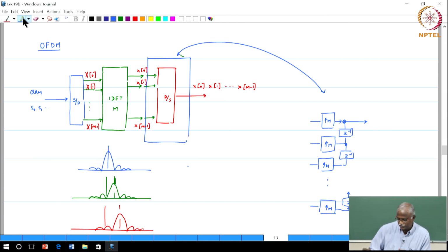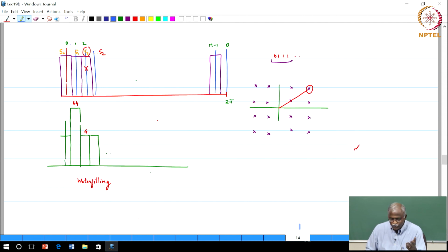with this particular structure. The IDFT and this structure actually implements a filter bank for you. So when you apply them, you automatically get the translation from time division multiplexing to frequency division multiplexing. And of course this also gives you a lot more insight into when you do not transmit on a particular carrier, and when you boost the power of a particular carrier. Again, all of these are flexibilities that come into play when you have an OFDM system.